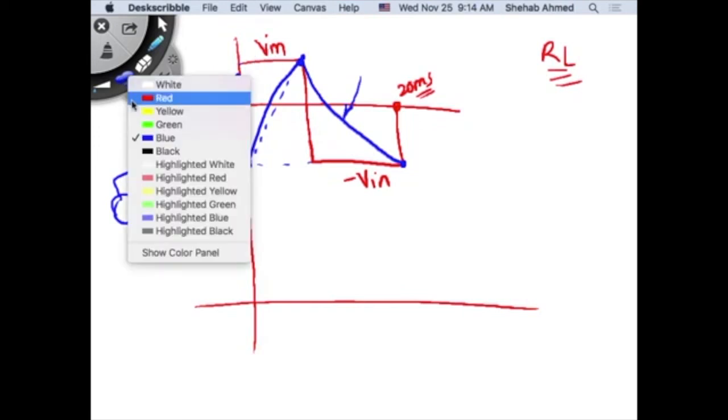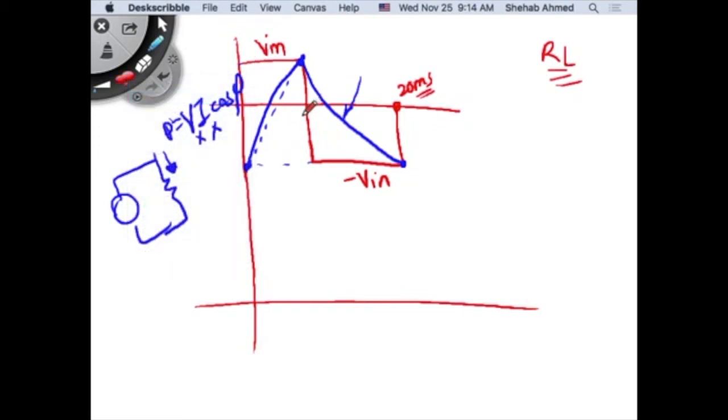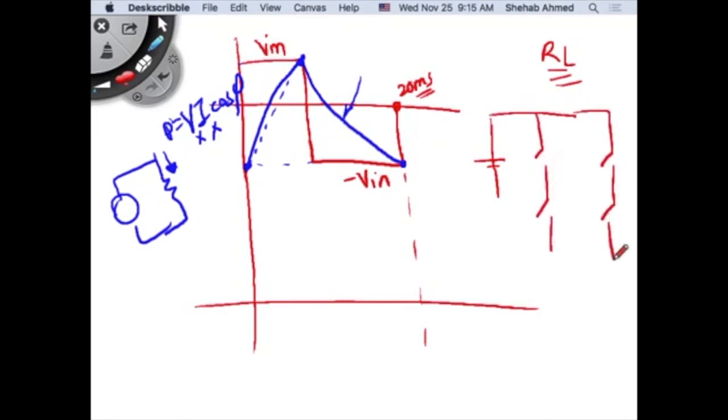So first we had this 4-switch inverter operating at the fundamental frequency of the output. I'm operating either 1, 2, or 3 and 4 together, right? So it's either Vin or minus Vin. What's some other option we talked about last time for operating this inverter? I can get Vin, minus Vin, and what else can I get at the output here? 0. If I turn on 1 and 4, or I turn on 2 and 3, I can get 0.